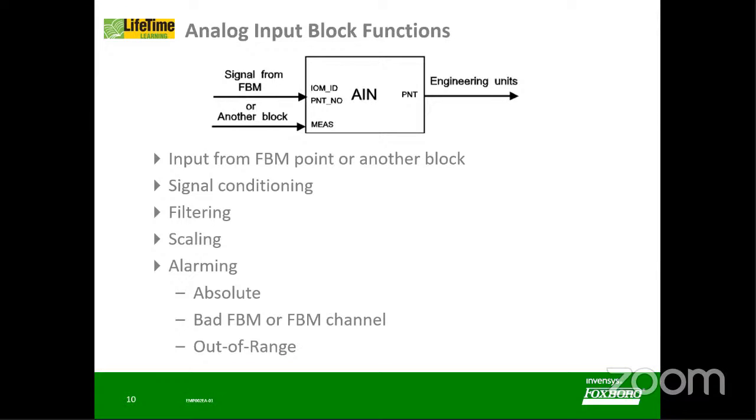So in case of a Foxboro DCS system, every control processor and every Fieldbus module will be defined with a 6-character name. It may be an alphanumeric name, like a CP name could be TRCP01, and one FBM name could be DICR01. Anything could be alphanumeric, but 6 letters or characters in size. So here you will define that FBM name and the channel from where this input block will read the data.